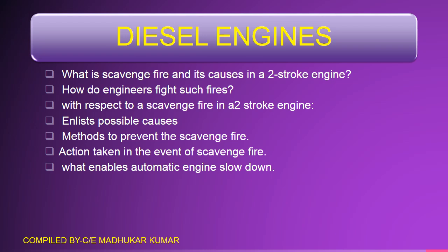Now the topic of diesel engines. This also is one of the important topics coming to you guys. So what is the scavenge fire? Its causes in two-stroke engine related to a scavenge fire. Very good question, very easy. How do engineers fight such fire? Sometimes you have the steam smothering system, sometimes you have the CO2 also.